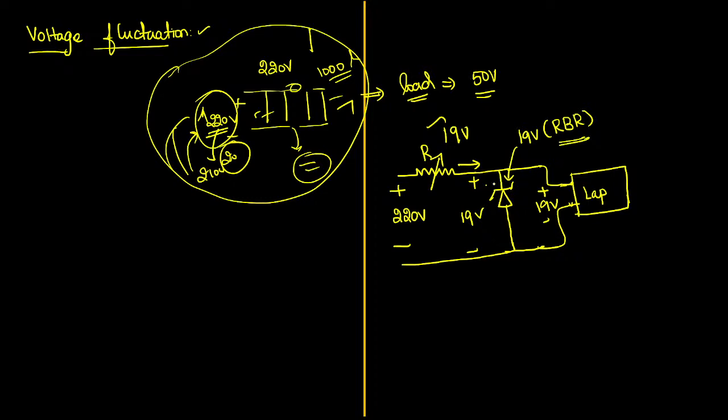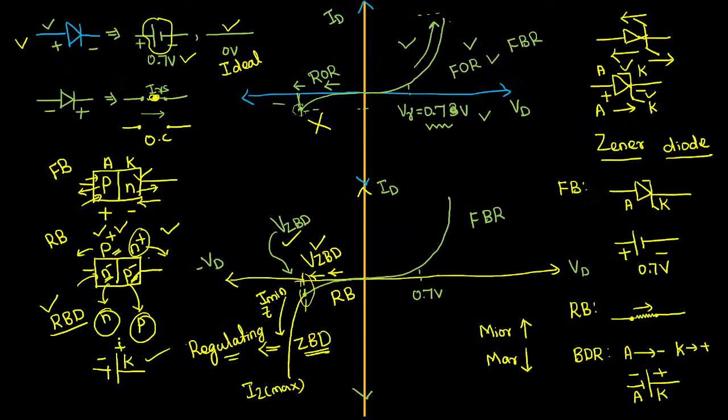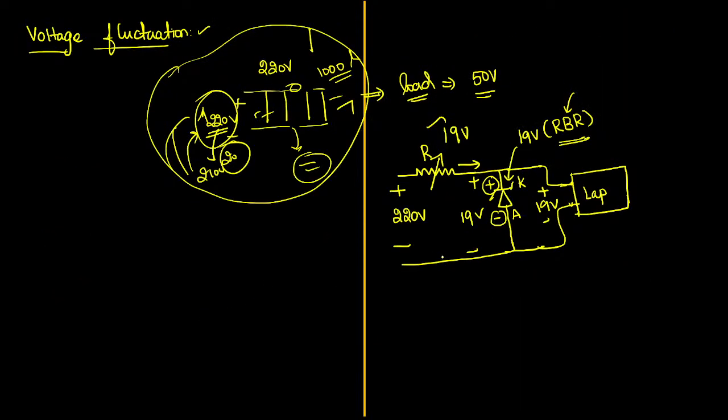See there, this is plus, this is minus. You know when it will happen? Basically this is called the anode, this is called the cathode. The cathode becomes the positive plate and the anode becomes the negative plate; when it operates like this, what region is it? That is called the reverse breakdown region. Just now we saw, I told you when the cathode becomes positive, the anode is going to be negative. I have explained the entire process, how it is happening. So the Zener diode must be operated in the breakdown region only.